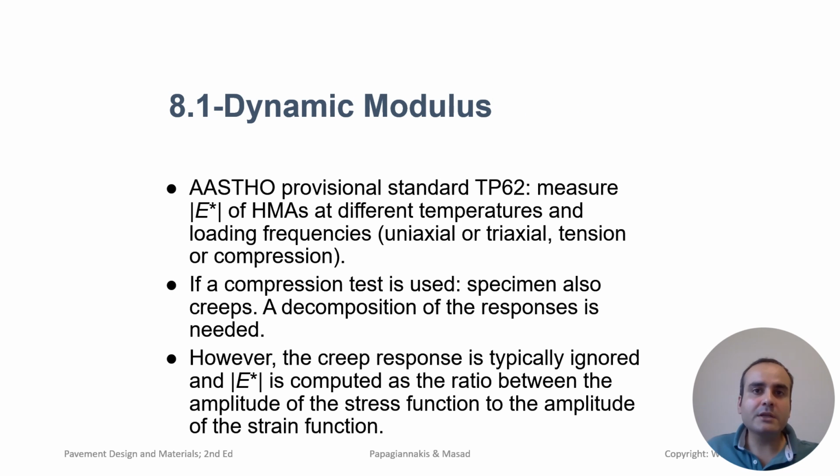The dynamic modulus represents the stiffness of the asphalt mixture under repeated traffic loading and is a critical property in predicting pavement performance. A higher dynamic modulus indicates that the asphalt mixture can better resist deformation, making it ideal for high traffic areas.